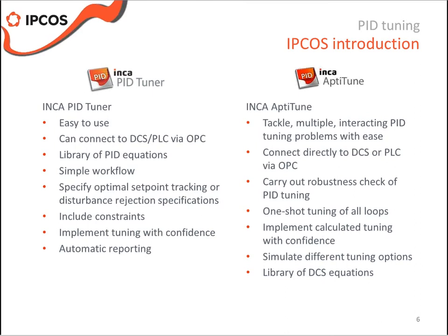They are both fairly easy to use. They have a very simple workflow. They can connect to a DCS or PLC via an OPC connection. We can also do things like check the robustness of the PID calculation that we put together or calculate. We can also implement and simulate tuning before we implement it. And there's a library of DCS equations that we can choose from a drop-down menu.